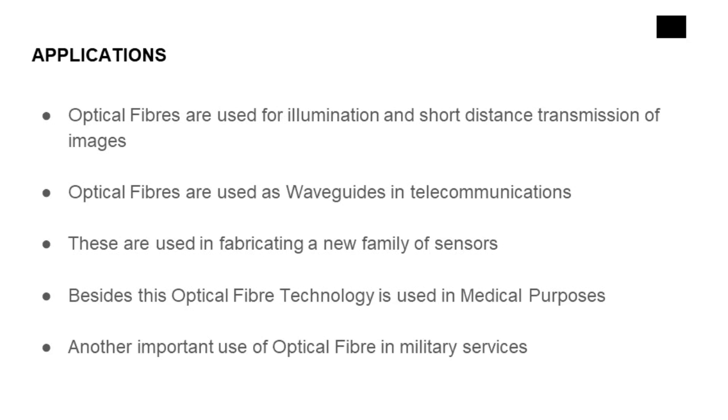Next, sensors. Optical fiber is used as a sensor. The variation of refractive index of the optical fiber under the influence of external forces is utilized in fabrication of optical fiber sensors. If the optical fiber is subjected to heating, the temperature causes a change in the refractive index of the optical fiber. As temperature increases, the difference between the refractive indices of the core and cladding materials reduces and light tends to leak away from the cladding.